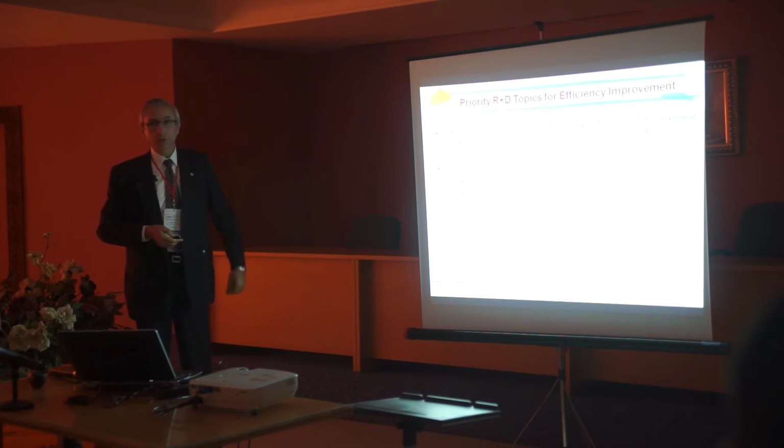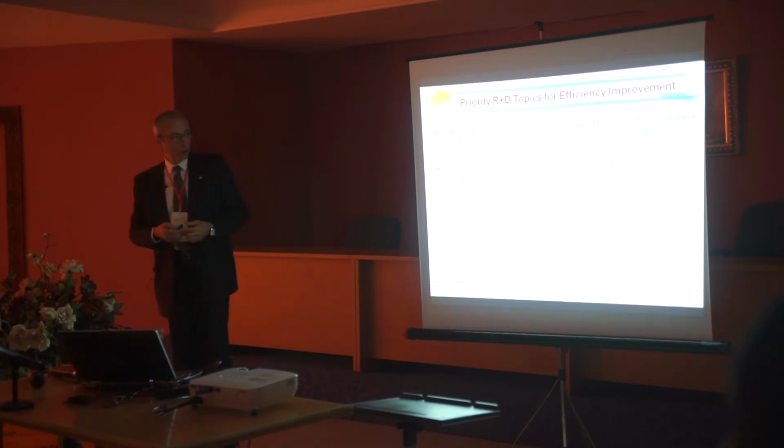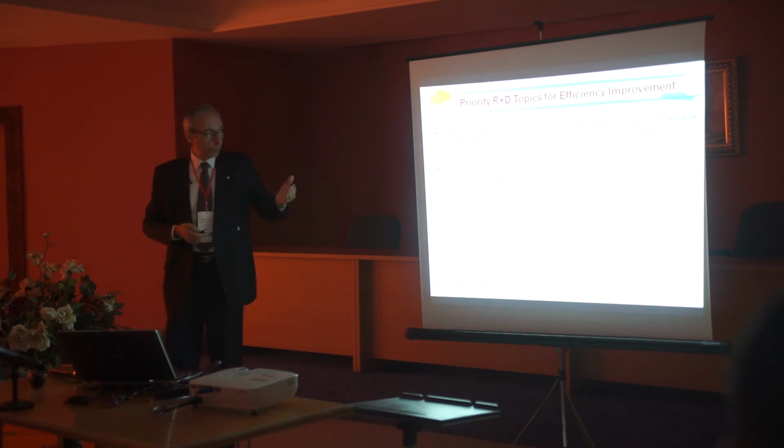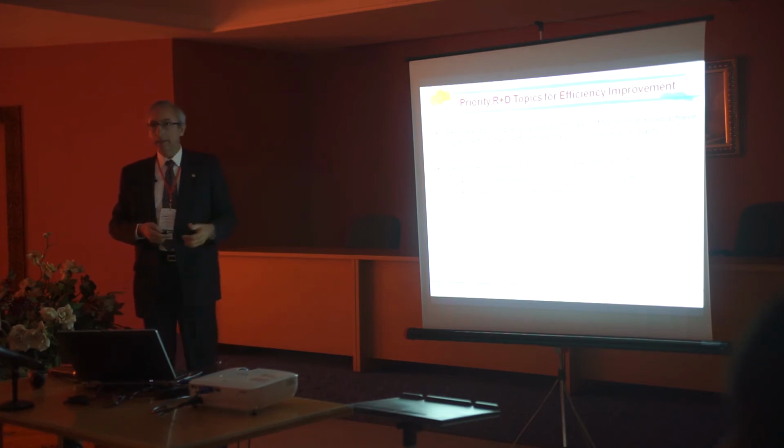Supercritical CO2 is also a promising option to increase the temperature, because there is no problem working with CO2, carbon dioxide, at 700 or even 800 degrees C in tower systems. This is why in the USA, supercritical CO2 is considered a very promising option to increase the temperature in solar thermal power plants with central receiver technology.